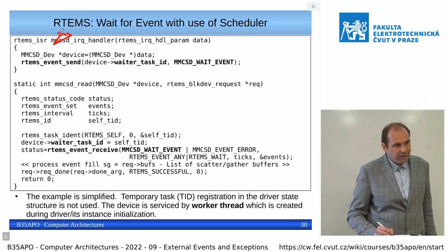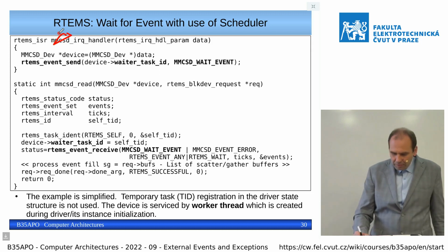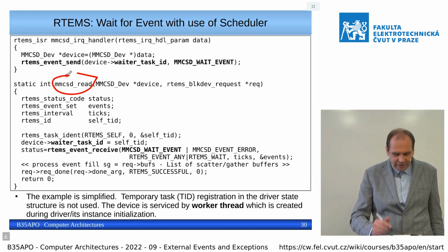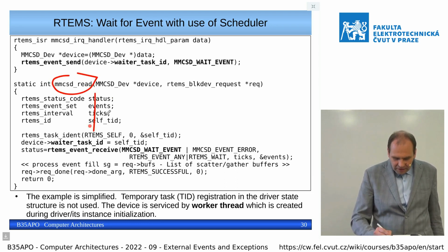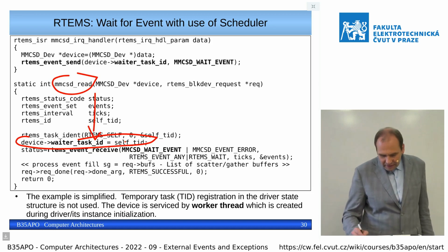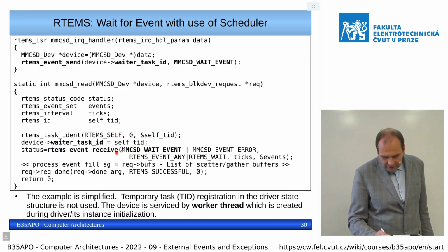So in this case, it is from our SD card driver from the infusion pump, and you can see again it is a read from the SD card, very simplified. We tell the device driver that a given task is waiting for the event. We say we want to stop and wait for the event, and it can be an error from the SD card or some other event and so on.